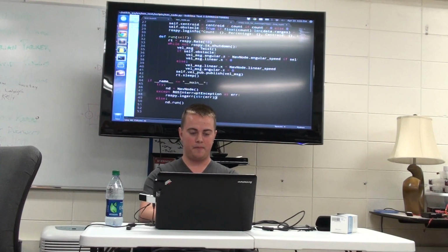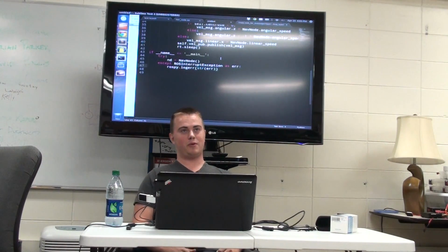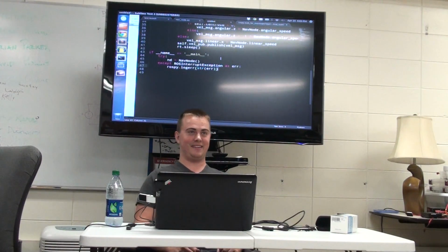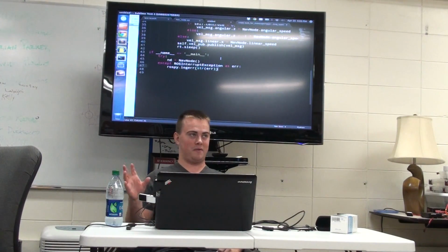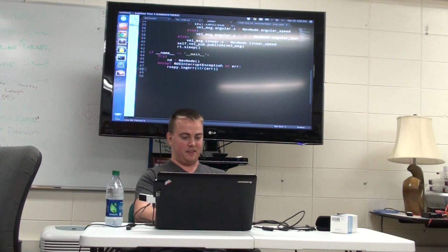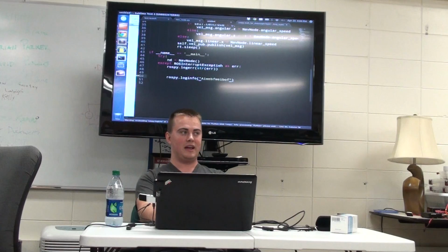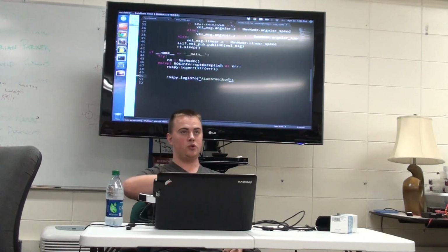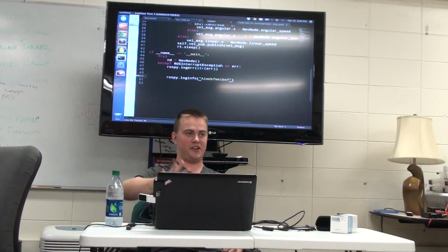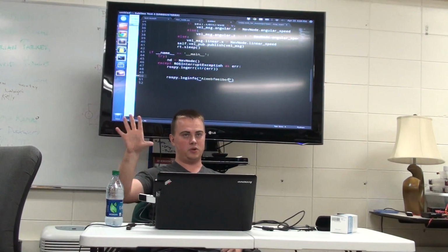And so the way we handle it is with this line. So another thing about ROS is that print statements don't always work either. If you're running it directly, like calling Python and your file name, print statements work fine. If you're running it through ROS, they don't always work. And so instead what we use is the ROS log. And that is called by using commands like this. So for example, rospy.loginfo and whatever string you want. That will then save that to the ROS log, which is a log of all the communications that are sent out by every node running at the same time, and it will also conveniently be printed to your terminal.